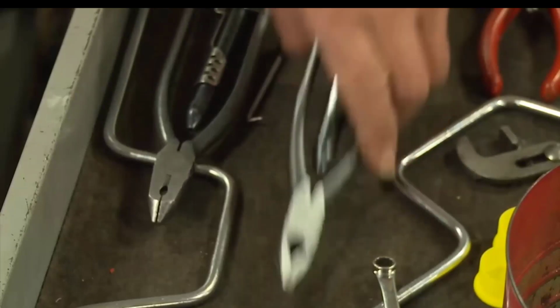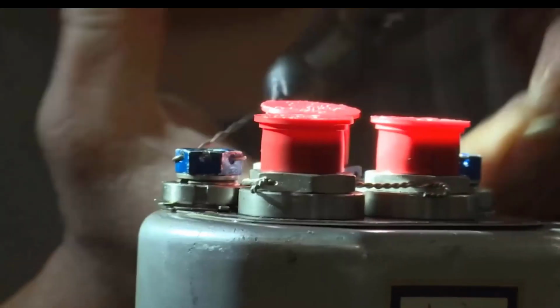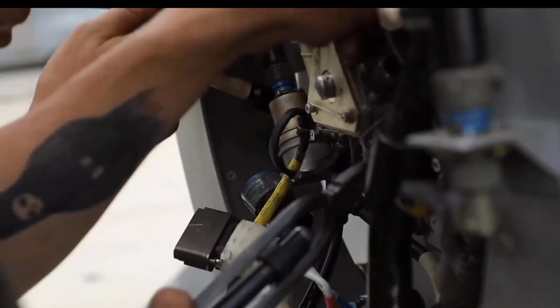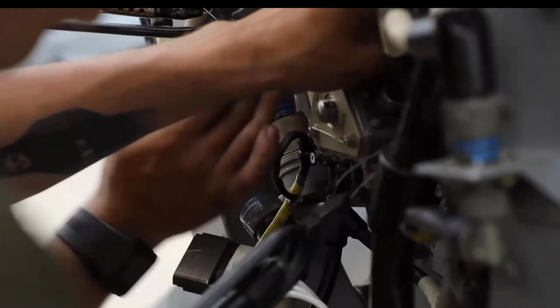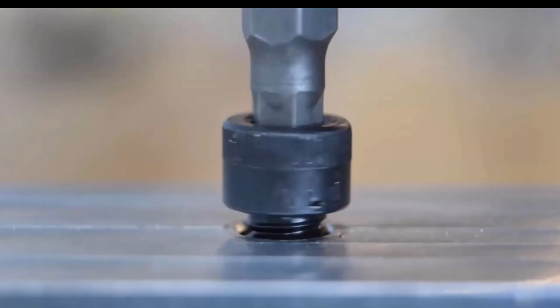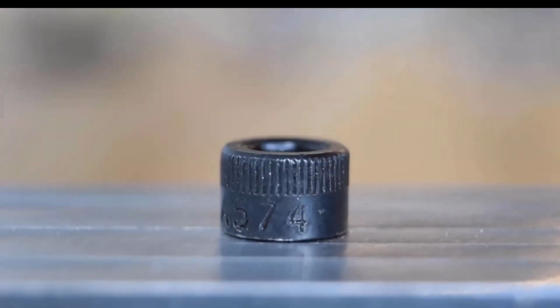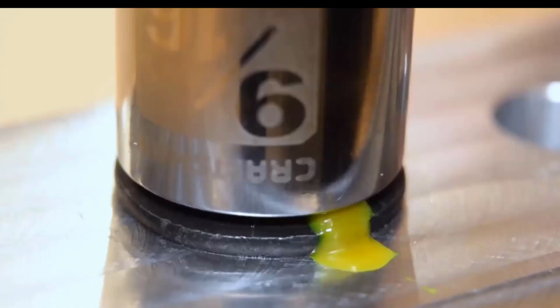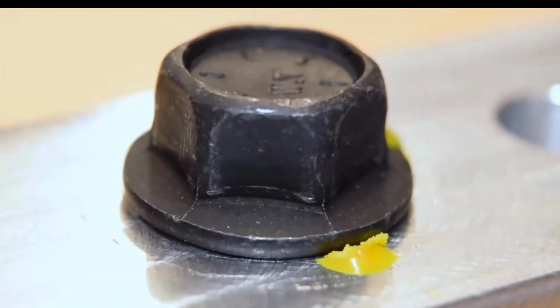When all else fails, the most effective way to prevent loosening is to physically prevent the fastener from turning after it's tightened. Aircraft mechanics use safety wire for this, and it's extremely effective as long as it's installed properly. One thing to watch out for is that a fastener that has been properly torqued looks the same as one that's only finger tight. A good practice is to mark the fasteners one by one as they are torqued. Then, a visual inspection will reveal which ones were missed. This special marking wax makes it clear when a fastener has been loosened, either by a person or by vibration.